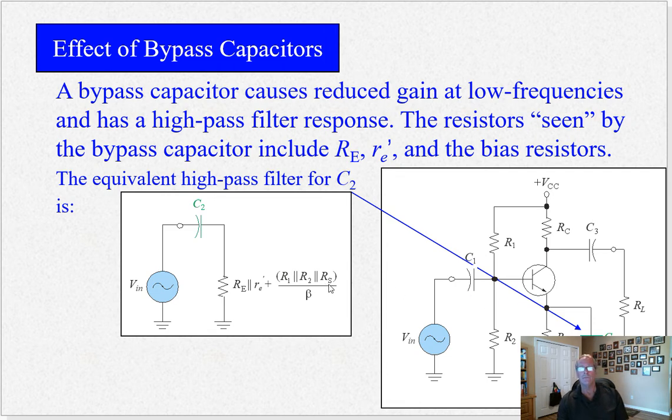What is RS? RS is the source resistance. It's not shown on this circuit. It's part of the generator in this case, whatever your source resistance is. It's a series resistor right here, okay? You have to take that into account because it's part of the circuit. There's no signal source that has zero output resistance, otherwise it would have infinite energy, which would be nice, but they can be pretty low. It can be in the ohms, but it's never zero, okay? Sometimes we can ignore it.